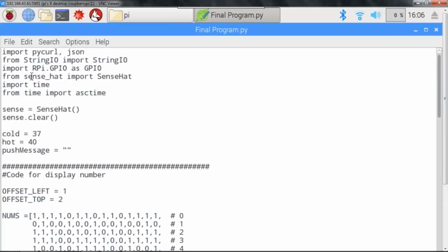And then you have the similar function. You have sense_hat from sense_hat and the time function. I'm establishing a connection here, as we have done earlier, between my Sense HAT and my application, and I'm clearing the screen on the Sense HAT. Sometimes, if you've executed a program before and stopped the execution, the display will still have the remaining data present on it. It stays stuck on the Sense HAT. So before we move on with the program, we'll clear the data out. That's what sense.clear does.